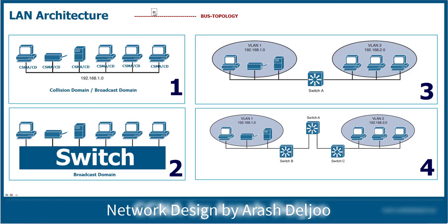In the bus topology, we used some type of coaxial cable, and also some special components such as terminators at both ends of the media. The terminator is actually a resistor that absorbs the remaining electrical signal in the line.